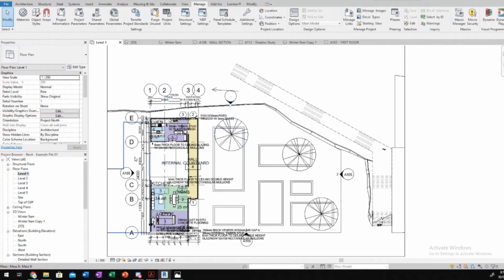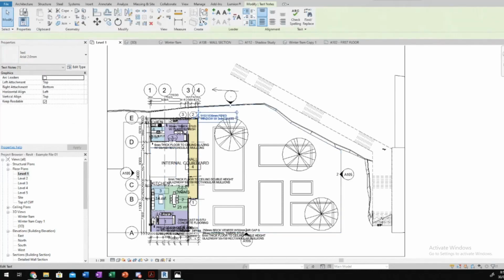But as you can see, it scales for the size of the page. It doesn't necessarily scale for the size of the drawing. So my one recommendation is, if you're ever setting up sheets and everything, set up the size of your sheets first, and place your drawings before you start your annotations, because you want to make sure that you're choosing the correct size.